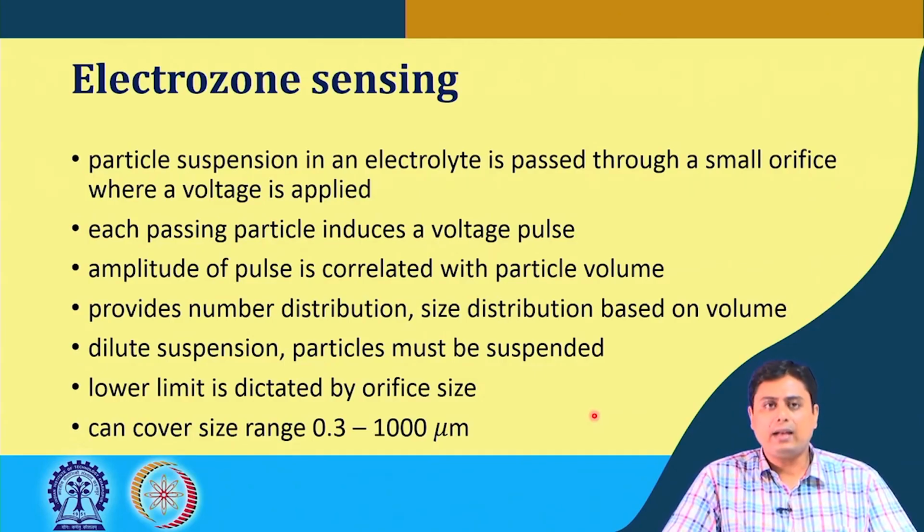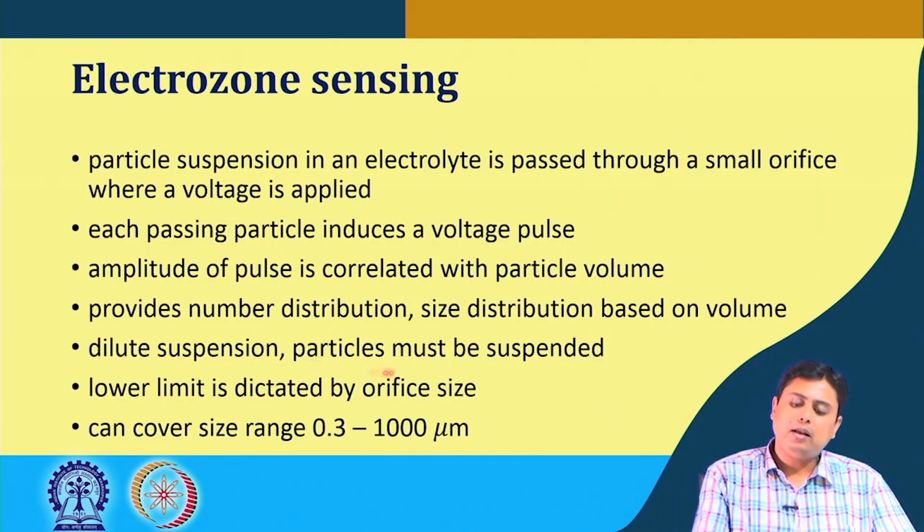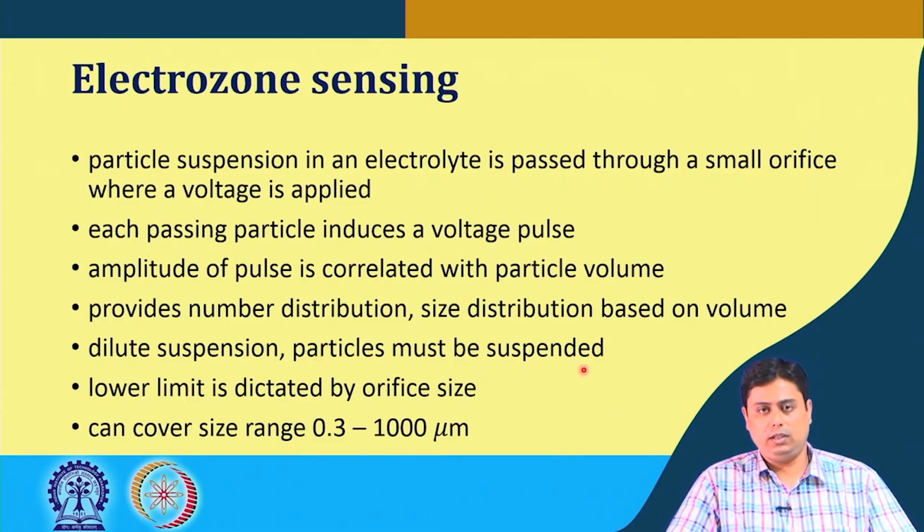The upper limit is dictated by the criterion, as I mentioned, that the particle must be suspended. If this is a bigger particle, it tries to settle down. So, you may have to change, in fact, you have to change the suspending fluid media. You have to take a more viscous fluid, so that it can be suspended for a longer time until you withdraw it through the orifice.